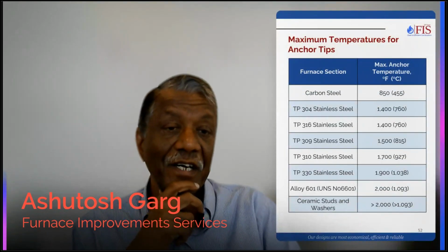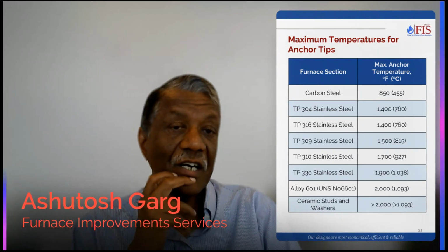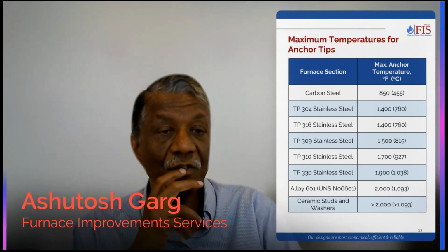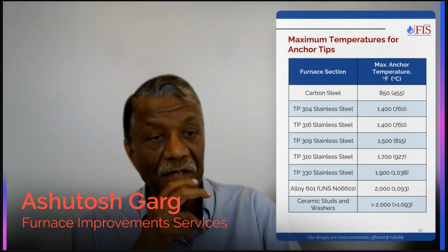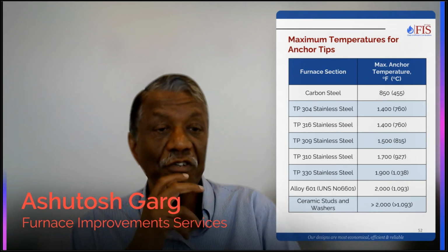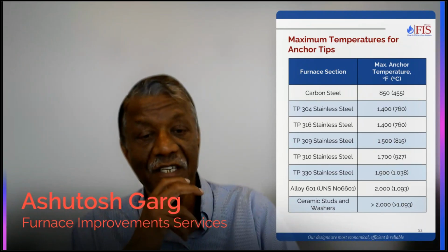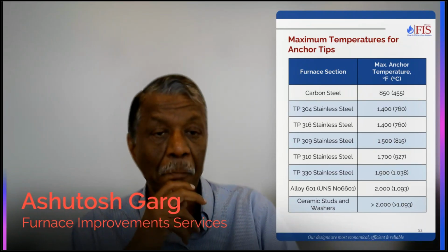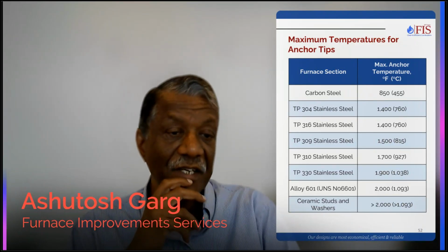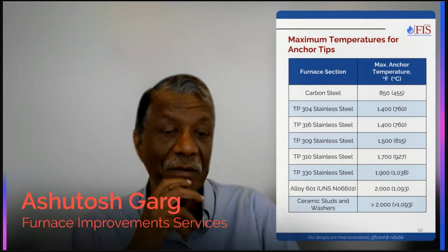The anchors depend on the maximum temperature. You can use carbon steel anchors, but normally end users will not allow you to use carbon steel anchors. Most of the time they will say stainless steel anchors no matter what. So those are decided by the anchor tip temperature.